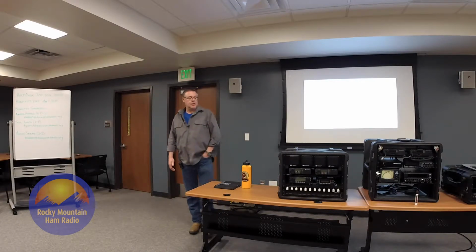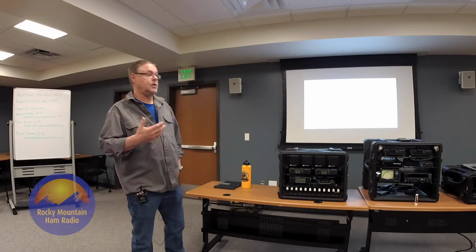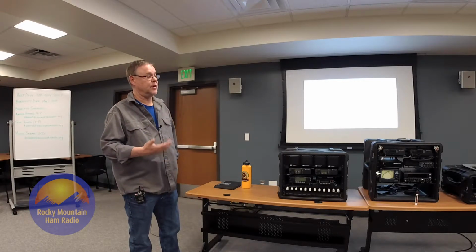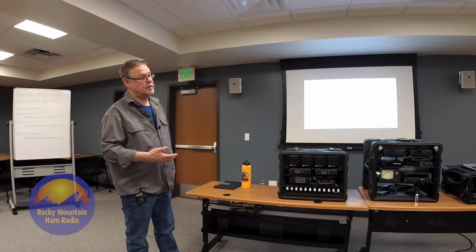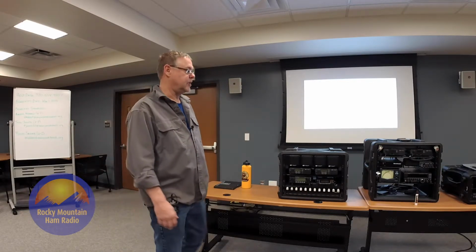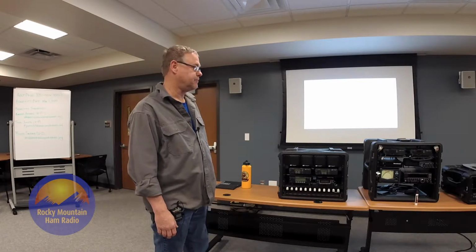But anyhow, so keep in mind the equipment you're going to use. Make sure you track your power requirements. That may be critical if you're going to run off solar, if you're going to run off batteries. If you're running off AC power supplies or a car battery with the car running, it's not as critical, but it's something to keep in mind. Keep in mind that weight usually equals more current, and current is what is going to work against you when you're designing your power system.